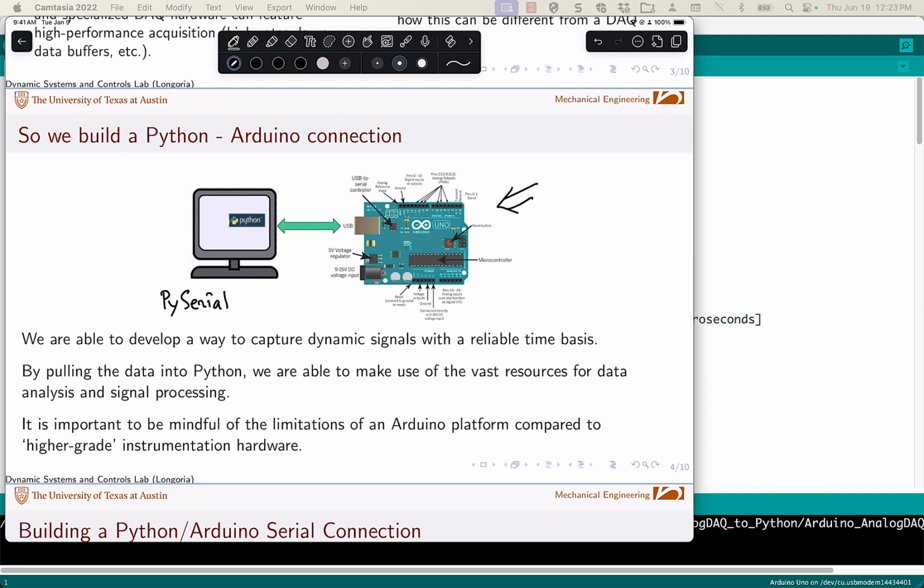That's what it's doing with the serial monitor and the serial plotter. In fact, sometimes when we're taking data through this interface, you can't use the serial monitor. I think one of the upgrades of Arduino IDE 2, for example, is that you could have two different serial communications going if you have the most up-to-date Arduino. So you possibly could be communicating serially with the computer and also showing the serial monitor. But whether you want to do that depends on the application.